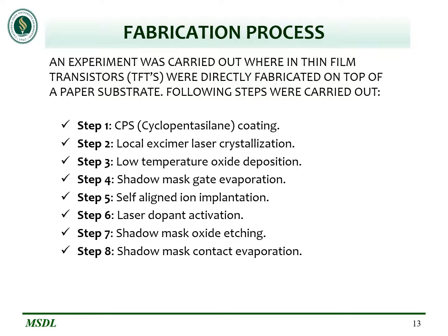As a liquid, the material has the potential to be applied directly on a low-cost, flexible substrate that generally has a low thermal budget, by annealing the liquid using excimer laser treatment. So far, electronics based on this material have only been demonstrated on rigid and high-cost substrates.